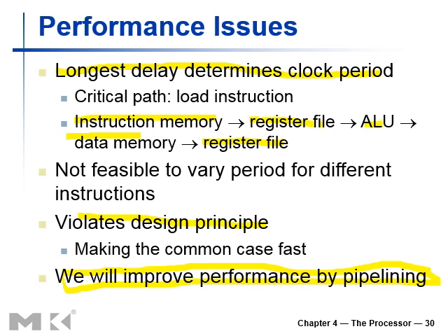so that we can execute the instructions not in sequential order, but overlap the execution of instructions, and we can set the clock cycle time depending upon the slowest stage rather than the slowest instruction or the critical path of the system. Now, how are we going to achieve that? We have to introduce some sequential elements in our design, and we will see how they are added, and what is the maximum limit of sequential components we can add so that our performance won't be compromised.